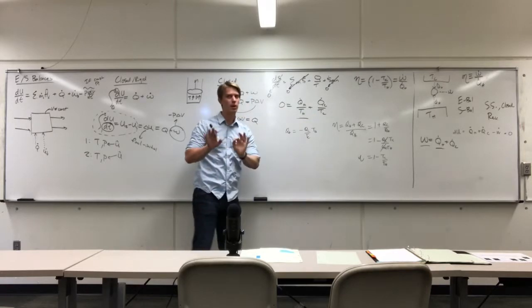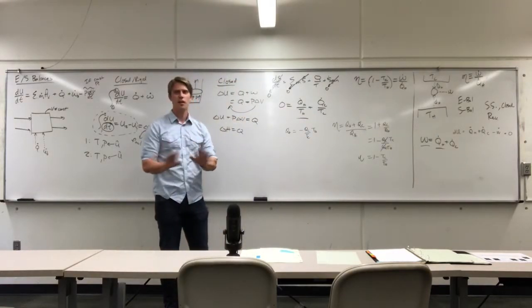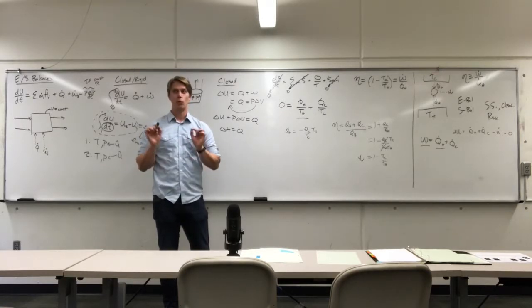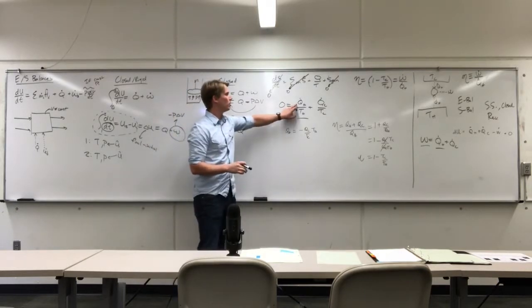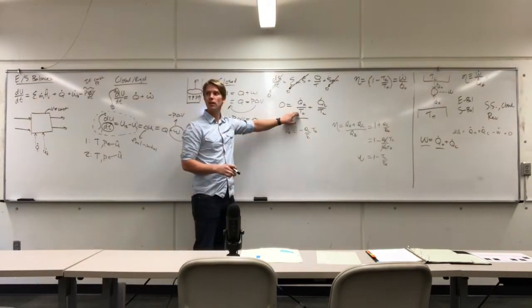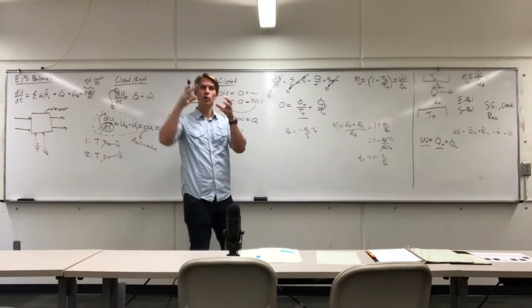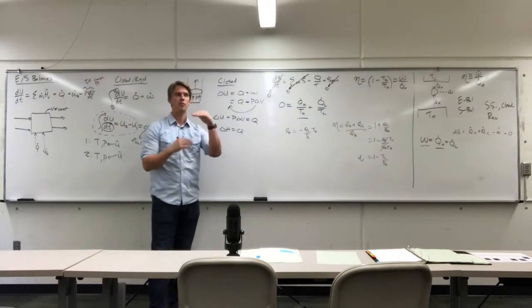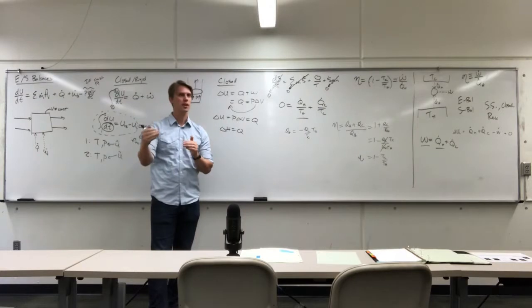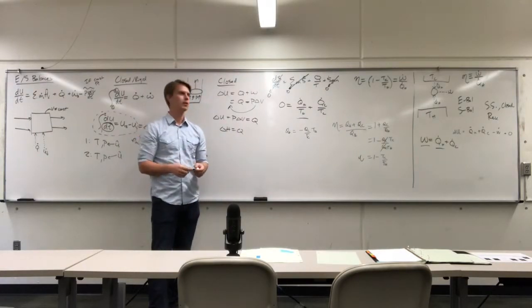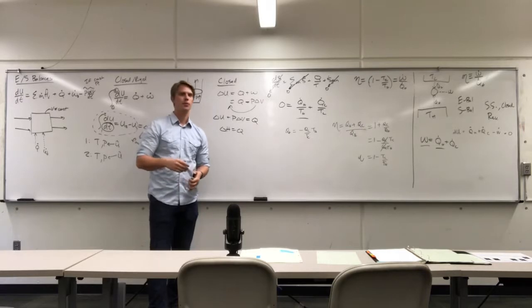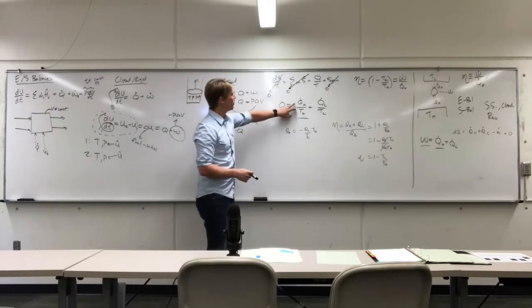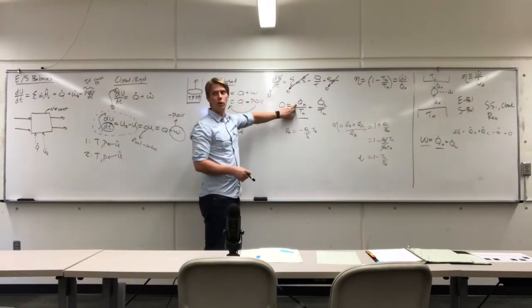But in general, for real processes, we will design basically all of our problems to avoid this at all humanly possible. In the real world, we have to heat stuff up by actually having a temperature gradient. Heat only goes from hot to cold. So when you want to design a process, you need to know what temperature gradient needs to be between the two sides of the heat exchanger fluids. There are heuristics in chemical engineering: if it's 500 degrees, you want a gradient of at least 100. If you want to heat it up to 50 degrees, you need a gradient of at least 5 or something like that. I don't design processes, so I don't know the heuristics quite well. But in real processes, we'll always try to avoid this.